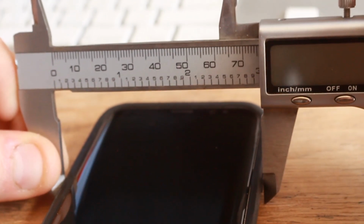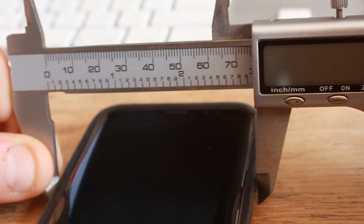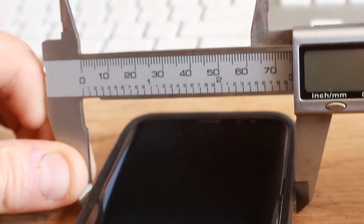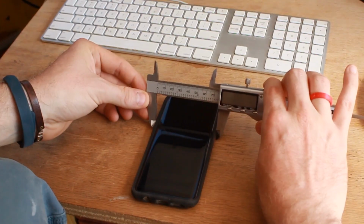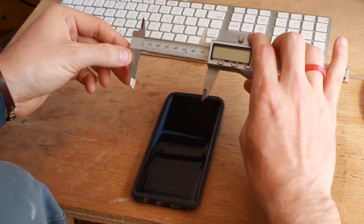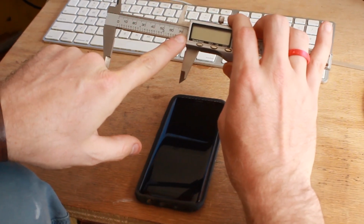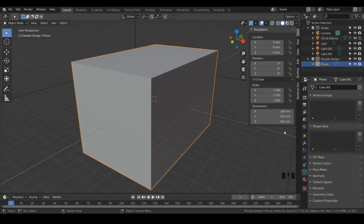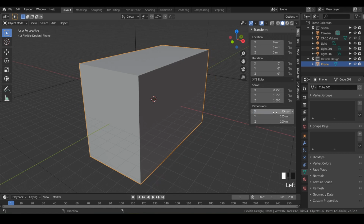And the next thing we want to do is take our calipers or our ruler and measure the width of our phone. Make sure you get the case, the buttons, anything, just get a good estimate and try and get as exact as you can. So the width of my cell phone is looking about 75 millimeters. So I'm going to come into Blender and just type in for the X value, 75, and hit enter. So that's 75 millimeters by 155 tall.